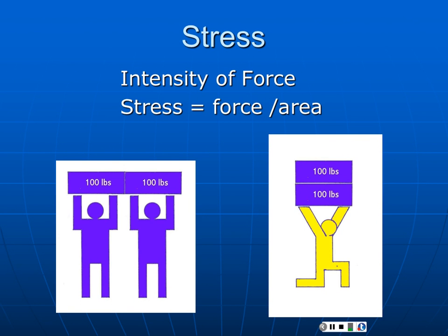So we begin with, what is stress? Stress is simply the intensity of force applied to a material. Look at this situation: in both cases we're talking about the same force, 200 pounds. Obviously the intensity is much higher for the poor yellow guy on the right. And so we normalize, force divided by the area, and essentially we end up with a quantity that is an intensity that tells us what's really happening in the material, even all the way down to the level of the bonds in the material.